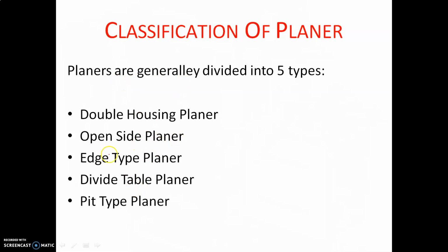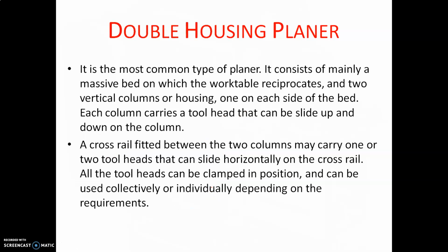So planers are normally classified into double housing planer, open side planer, edge planer, dividing table planer and pit planer. So these are the different types of planer. Planers are normally used for heavy work with high power consumption. Double housing planer is the most common type of planer.